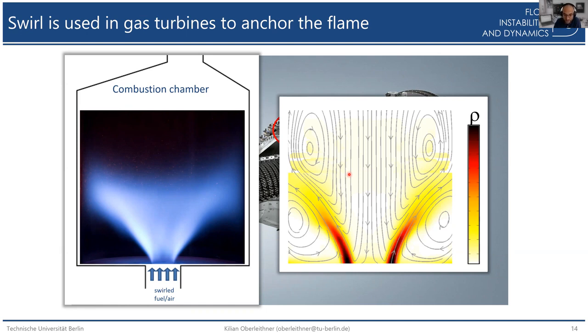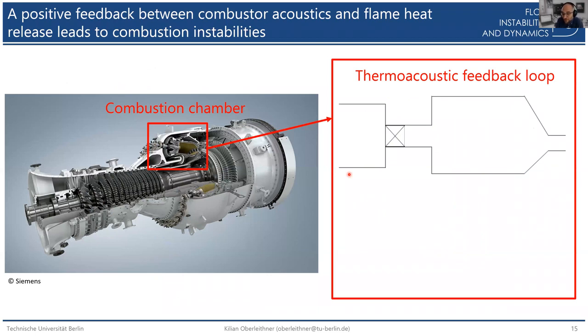But before we come to this, I need to introduce you also to the problem of thermoacoustics. In very basic words, it is a coupling of the acoustics of your combustion chamber with your flame, with the heat release of the flame. If this coupling is constructive, you get very strong pressure oscillations, a resonance of the entire combustion system, and that is very harmful to the combustor, and you cannot run the gas turbine at such an operating condition. So you definitely need to take care of this problem.